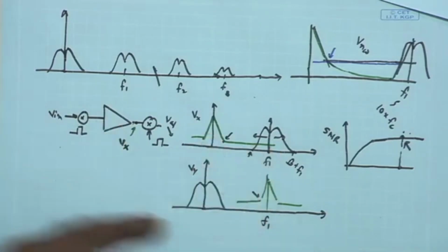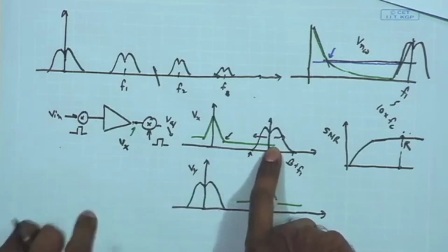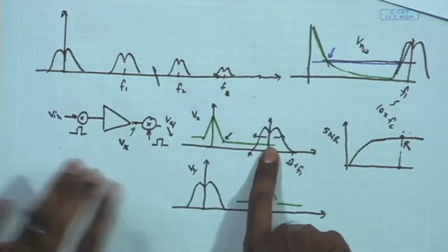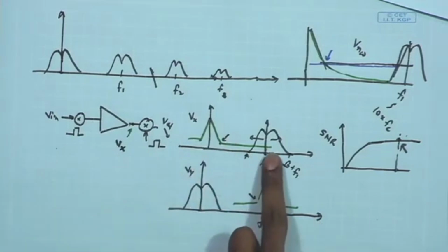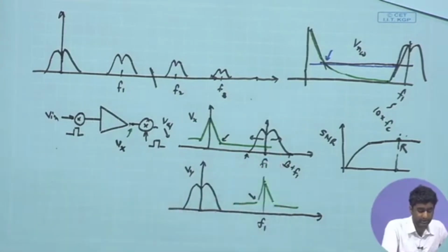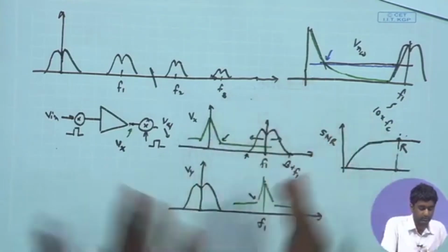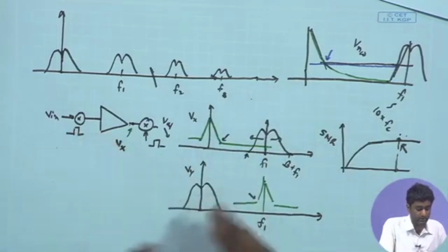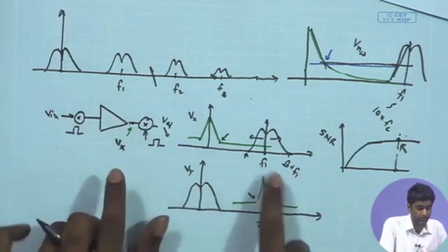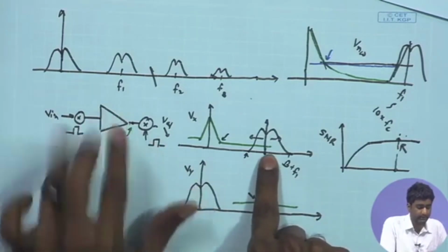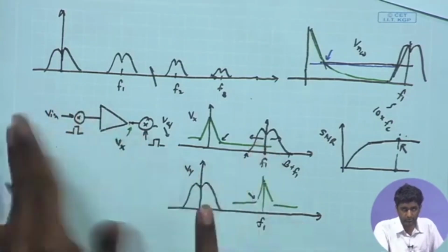Otherwise, likewise you have other scenarios as well, where you are having the compensation with the help of CC. There also you may need to relax the compensation capacitor value, and that is going to trade off with your phase margin. So, if we try to go for larger and larger chopping frequency, it has a negative impact on the overall open loop gain of this amplifier that you can achieve. And once again, you need to make sure that at this frequency, while satisfying the bandwidth requirement, it is able to meet your stability criteria, it is able to meet your phase margin. So, both of these are getting tightly coupled.